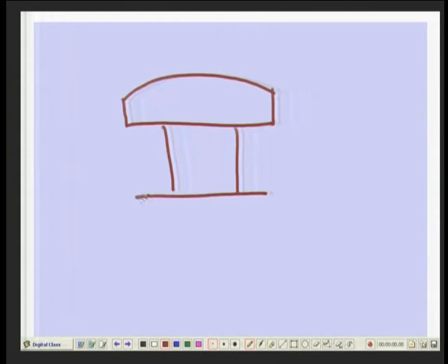what is important for you to know is in the d axis there will be a steady flux. Okay. Then whenever the short circuit happens there will be a tendency for variation of flux, but to maintain the flux constant the dampers will now first be effective. Okay. So, initially dampers will start carrying current,